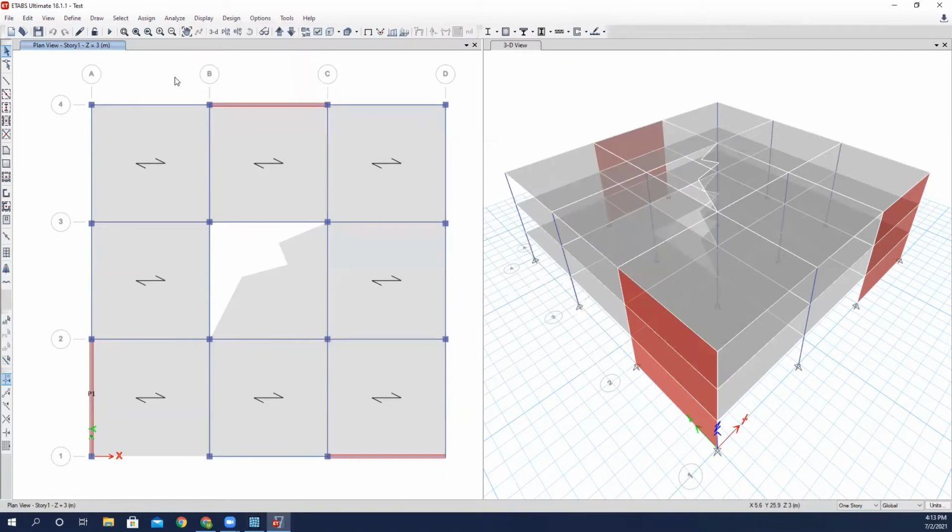Selection of the base point is an important step in generating the grillage model using AutoDiaphragm. Using the base point, the program will understand where your vertical supports are in reality. For example, if you have a wall here, a wall here, and a wall here, these are the supports for your diaphragm actions. One way for the program to understand your supports is through base points. How the base points work, I will explain in more detail.